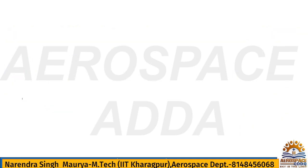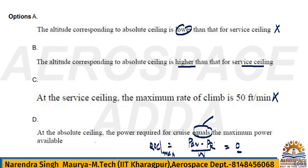So check the option here, absolute ceiling, obviously rate of climb will be 0. And when will it be 0? When power available and power required become equal. And yes, so this option D is also correct. So what is the correct option here? B and C. B and C is the correct option.